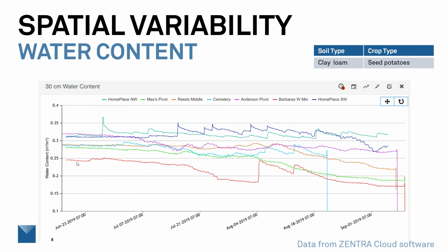We see a variation that when I look at it, I don't see that much variation, but maybe when you look, it'll seem like quite a bit. It's about a range of about 7% water content. And of course, through the season, we see a lot of variation. But right here, these sensors are all installed after a pretty wet winter where we had a lot of snow and then we had some rain. So all of these soils I would expect to be at field capacity. And yet suddenly we're looking at water content that varies quite a bit.